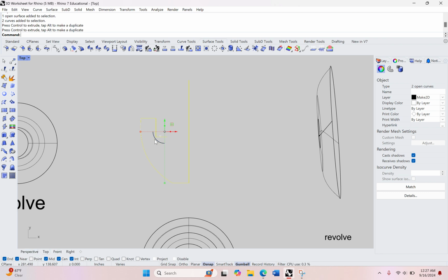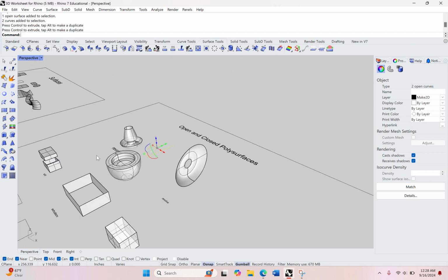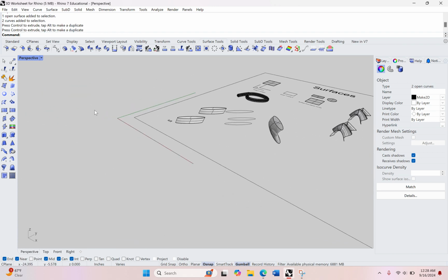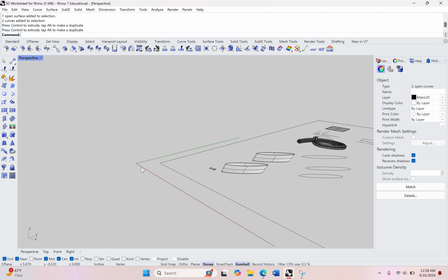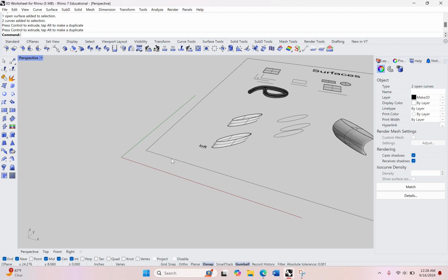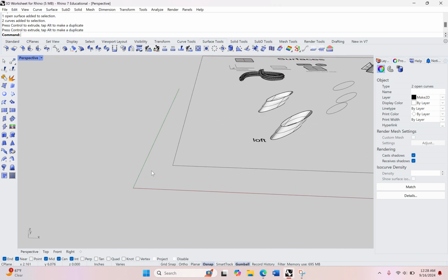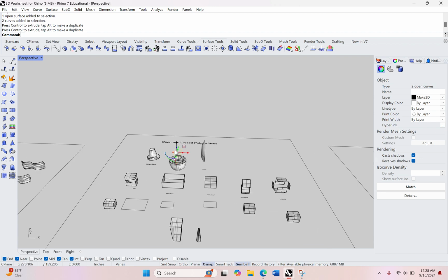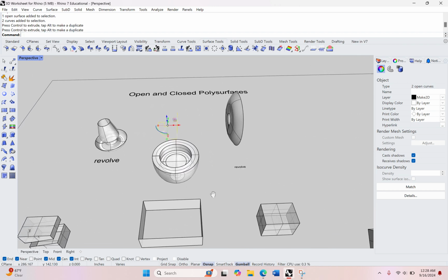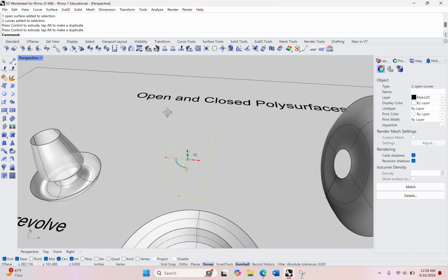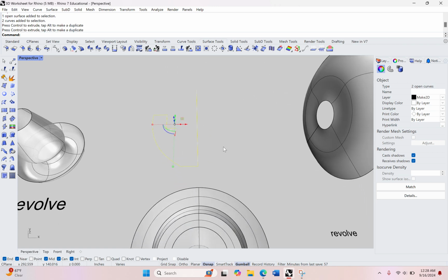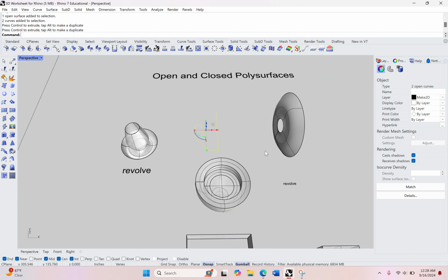And by the way, when you establish curves from the top viewport and then check them in perspective, they are always in perfect agreement with the origin of our Cartesian plane here, the X and Y axes indicated in red and green, which by default populate on your workspace when you open Rhino. Everything that you create from the top viewport is going to be Z-axis neutral. It's going to start at the origin, and you'll have one basically flat place for all of your 2D stuff to go. And it's a good organizational tool.